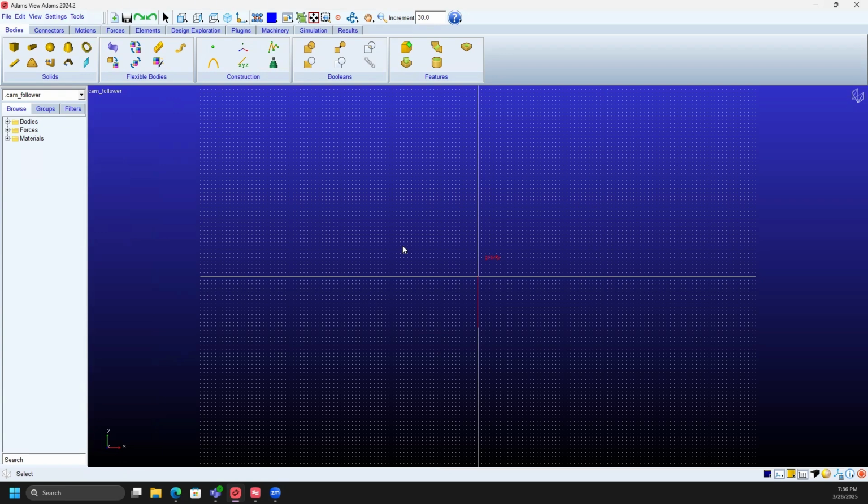Then you're going to create a closed body spline under bodies, which will be actually under bodies construction. Then you're going to select new part, turn on the checkbox next to close, and create. Then click on 13 points in the table below. 2, 3, 6, 7.